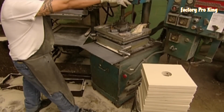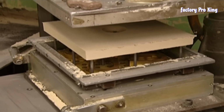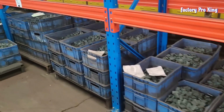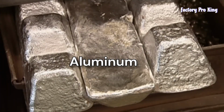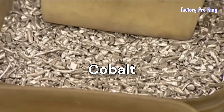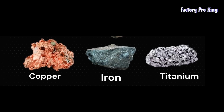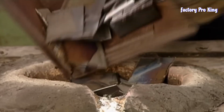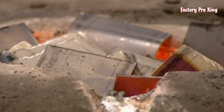Creating magnets from alloys is a detailed process involving several critical steps. Here's an overview of how it's done. For alnico magnets, primary constituents are aluminum, nickel, and cobalt, with additional elements like copper, iron, and titanium. The proportions of these elements are crucial as they determine the magnetic properties of the resulting alloy.